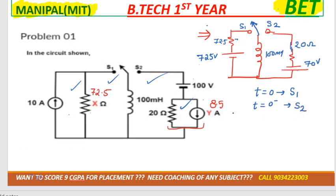So as I told you the steps, at t equal to 0 minus we need to draw it, and at t equal to 0 minus the switch is connected to S2, so the inductor will behave like a short circuit, resistor as it is, battery as it is, and t equal to 0 minus is the steady state, and in the steady state the inductor will behave as a short circuit.